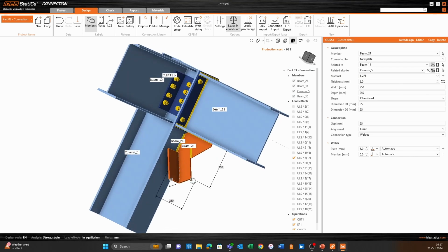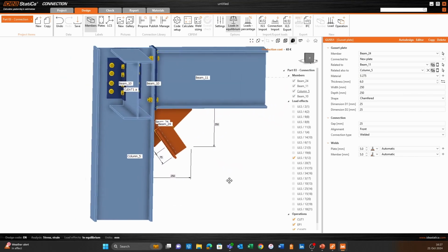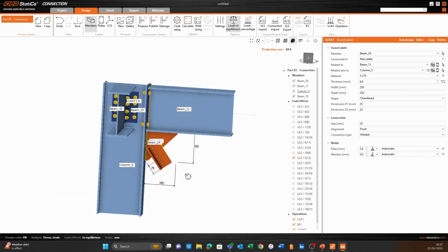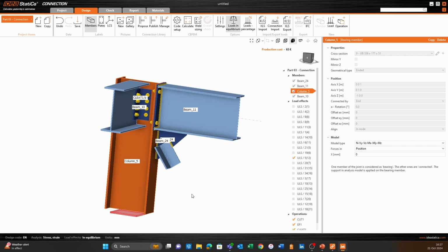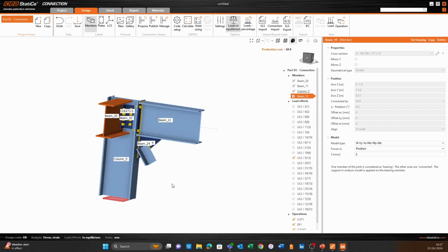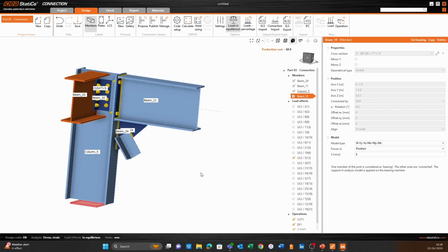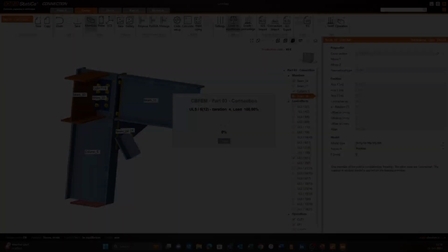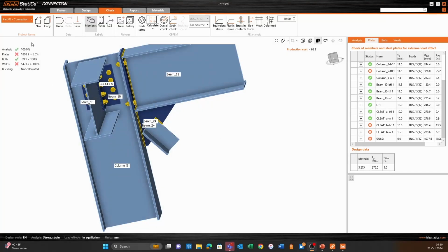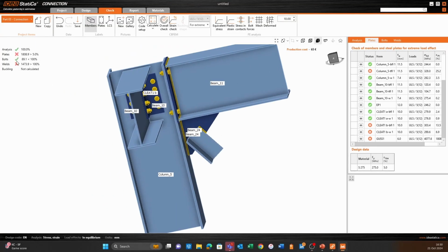And that is it. That was quite quick. So what I'm going to do now is I'm going to start the analysis, and let's see how this goes. I just want to see, okay, this is my bearing member. It's all good and well. All right, so I'm going to run with the analysis, and then I'll be back with you again once it's finished running. And we are back, and everything ran normally, but we can see we are exceeding our limits by a massive margin. Our bolts are fine, but our welds and plates are a problem.